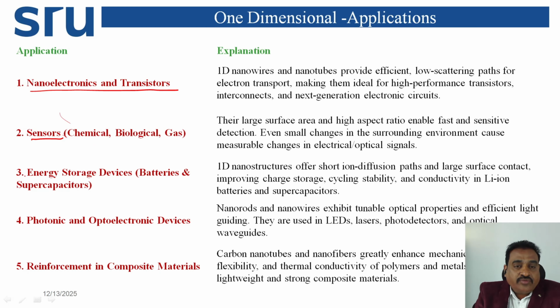One dimensional nanomaterials are used in energy storage devices. The devices are batteries and supercapacitors. One dimensional nanostructures offer short ion diffusion paths and large surface contact, improving charge storage, cycling stability, and conductivity in lithium ion batteries and supercapacitors.